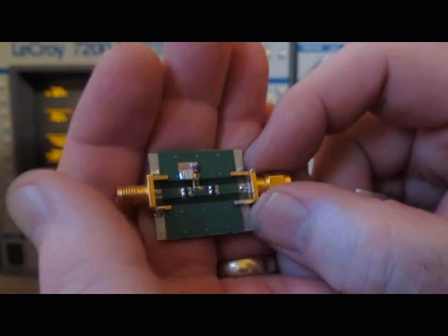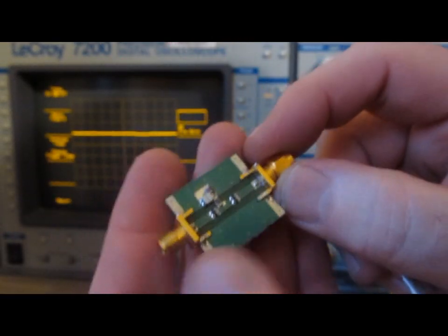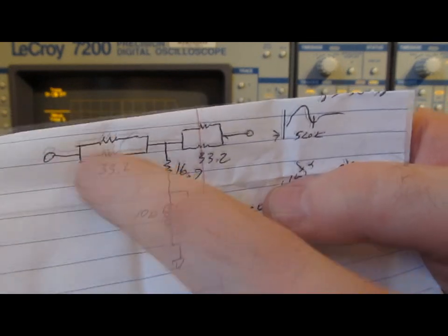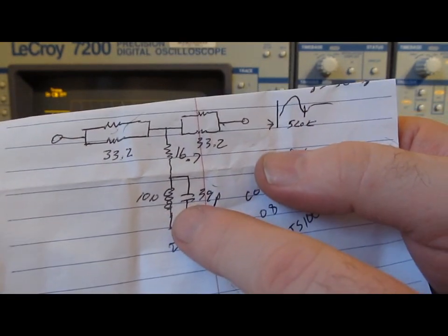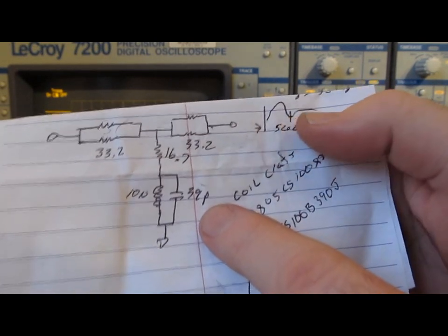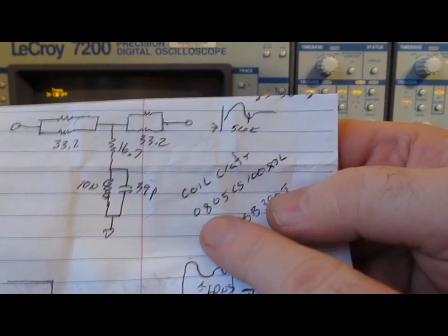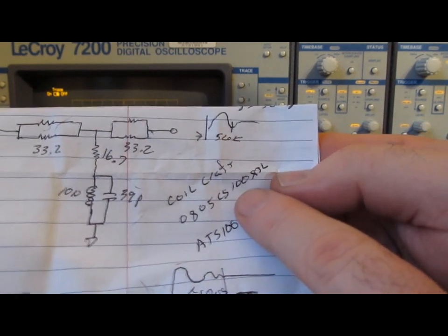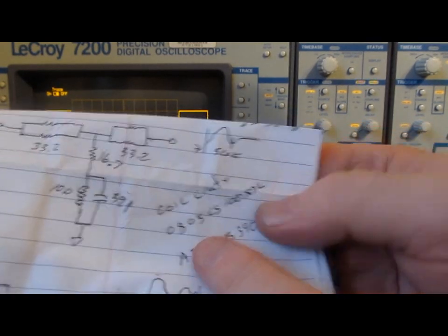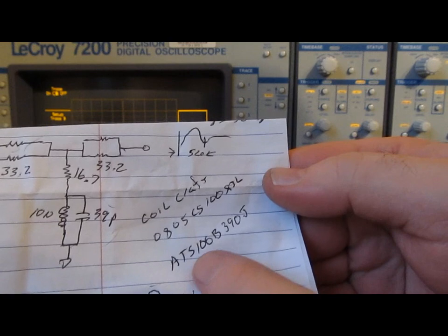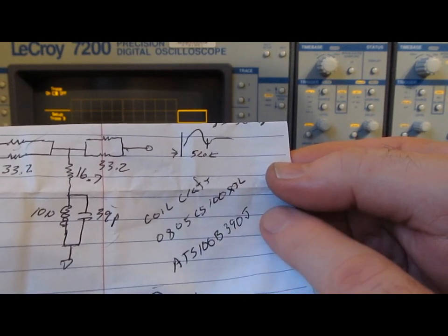So this is a second circuit I put together to test our eye diagram software. This is the schematic for it. So essentially it's nothing more than a splitter, and then you can see I have a small tank circuit. This tank circuit is made up of a 10 nanohenry and a 39 picofarad capacitor. The inductor is made by Coilcraft. It's part number 0805CS-100XJL. The capacitor is made by American Technical Ceramics. This is a part number ATC 100B 390J.